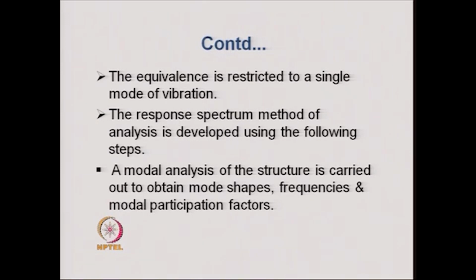The mode shapes and frequencies are very routinely obtained for any given structure, provided the mass matrix and the stiffness matrix corresponding to the dynamic degrees of freedom are known. And once we have the mode shapes and frequencies, then one can find out the mode participation factor for each mode, which we will see a little later.